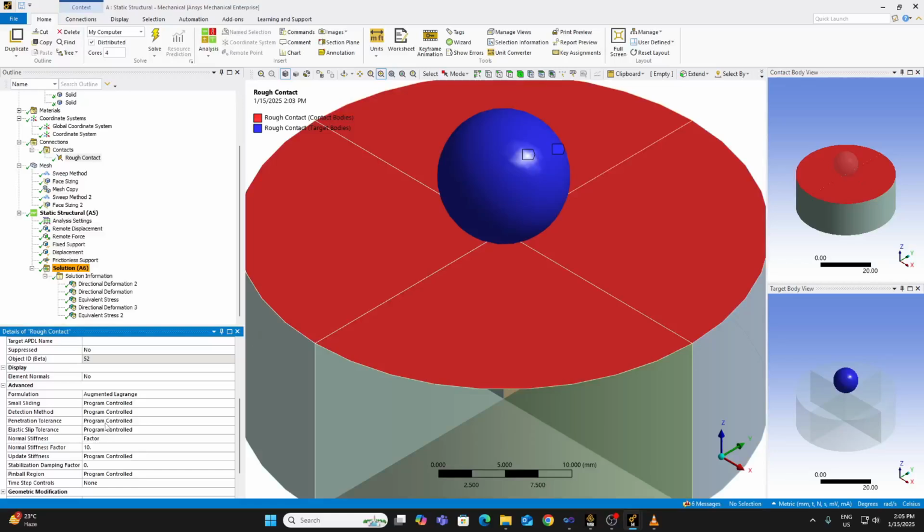Now again, penetration in this particular simulation can be of significance, because that means the deformation of the specimen surface would be less than the displacement of the indenter. Ideally the indenter should descend as much as the top surface is deforming. But if there is some amount of penetration, the indenter penetrates the surface of the specimen and moves a little bit inside of it, which means there would be a discrepancy between the deformation of the specimen surface and the displacement of the indenter. Of course, there would be some amount of error if you are going with anything but the normal Lagrange method.